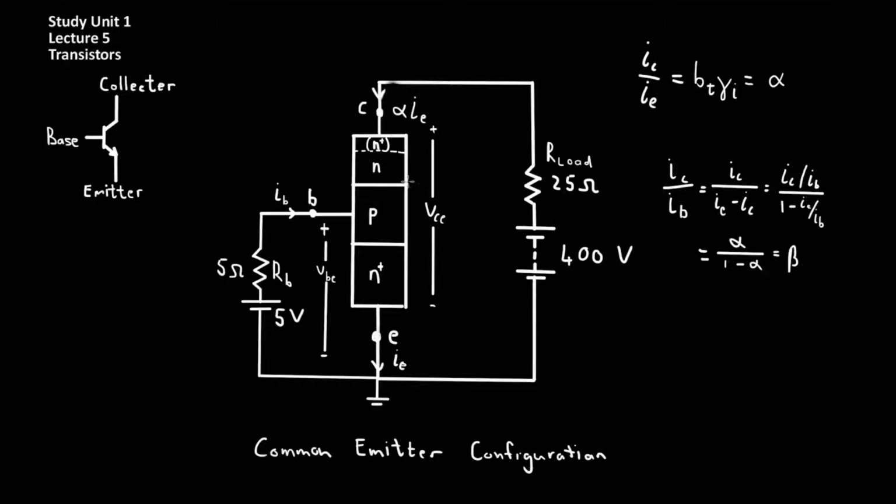The basic bipolar transistor consists of two PN junctions stacked into a single piece of silicon. There is a central p-doped region, an N region, and a heavily doped N+ region. The heavily doped N+ region is known as the emitter, the P region is known as the base, and the N region with a heavily doped N terminal is the collector. The heavily doped N region, or the emitter, serves as the main source of electrons which are injected into the emitter base junction over here.